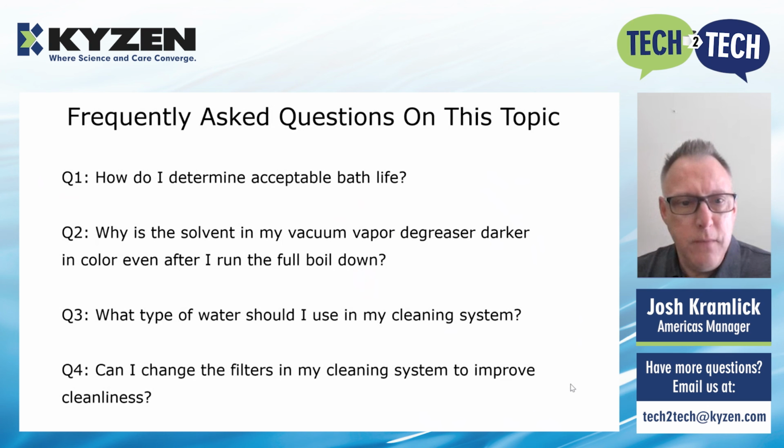And question 4, can I change my filters in my cleaning process to improve cleanliness? Potentially, yes, but note the differences in performance of different filter brands, the differences in nominal versus absolute filtration, and of course, the impact on the pump performance in the system.